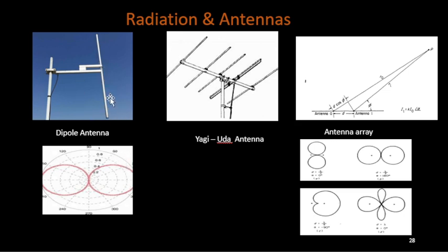So we'll be discussing this kind of dipole antenna. This is one simple conductor bar that could be used as a dipole antenna. Through this wire, if we apply a certain current I, this current should be AC current. If it is AC current, then this conductor will radiate EM wave on this side. This is a simple dipole antenna. What is the meaning of dipole, I'll discuss later on. So two-pole kind of thing. This is one radiator, main radiator.